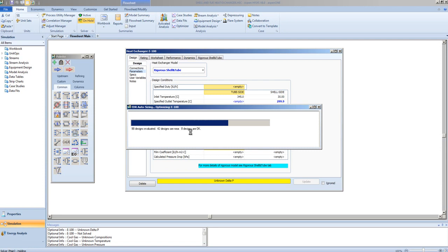These designs may have UA values that are higher than the UA value desired, and as such, the designs will be modified slightly by changing tube length or by changing tube diameter to determine which combination is best suited to the service.